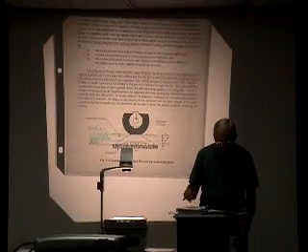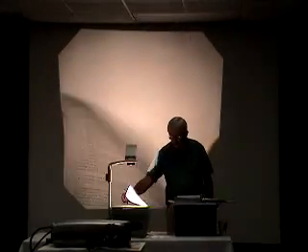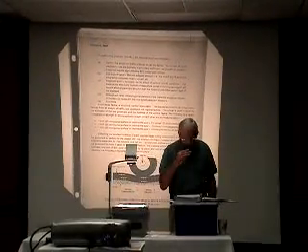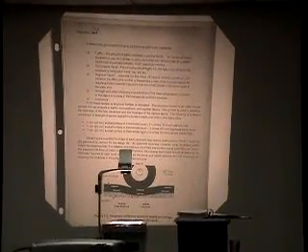Over on the next page, it lists at the top of page 4 the major things, actually 5, that go into pavement design. One of them, of course, is the traffic. And when you're designing a pavement, when you say traffic, it's primarily the number of trucks that are going to be using that pavement that really influences how thick the pavement needs to be.